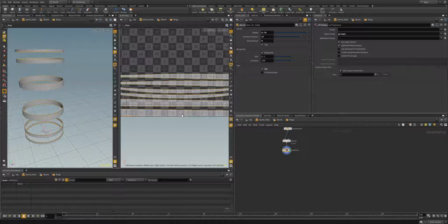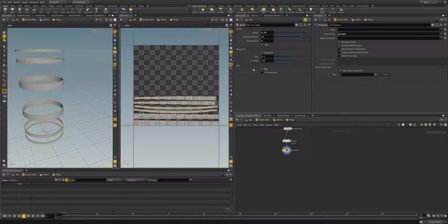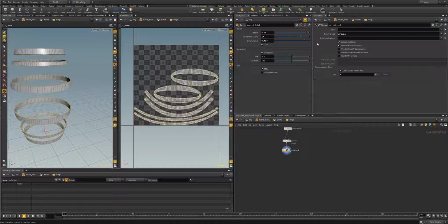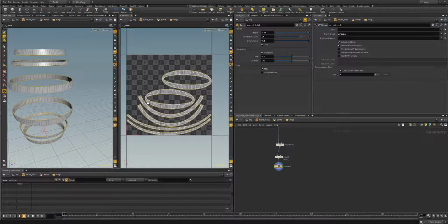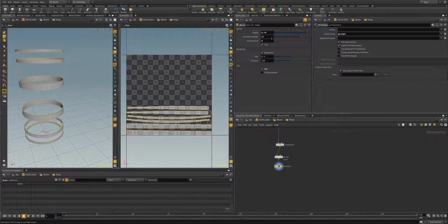But I really want what this bottom one is doing for each one. I want a nice straight barrel hoop UV for each of my hoops. And as my bow amount increases, I'm getting more and more curvature with all of my rings, and it seems not really working the way that I want it to. So there's probably a better way to go about doing this. And as we saw, doing this actually seems like it's almost working when the tube or my barrel is straight.